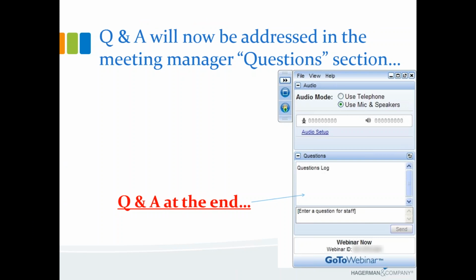The 3D sketch is initialized using the same pull down where the 2D sketch command is. So you've got two different icons there. You have a 2D sketch icon, and then just underneath that you have a 3D sketch icon. A lot of people don't even realize the 3D sketch is there, but there is a pull down arrow to the right of the 2D sketch icon, and you'll see 3D sketch listed underneath. Fair warning, when you go into one, it remembers what you were just in and it keeps it there until you switch to another one. So if you start out with a 3D sketch, that icon is going to be the default icon as long as you have Inventor open in that part file.